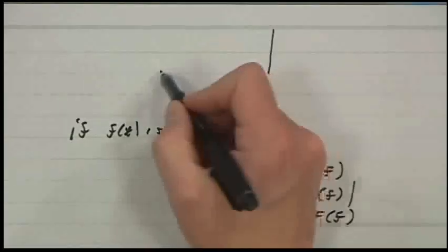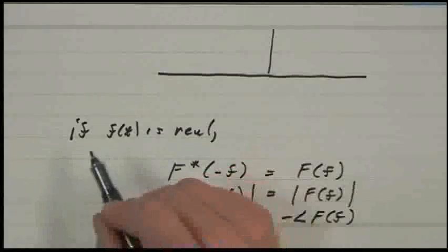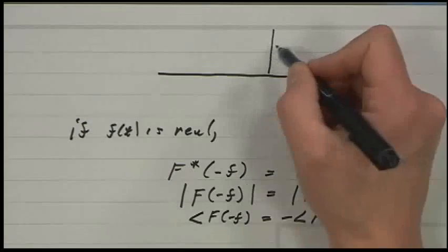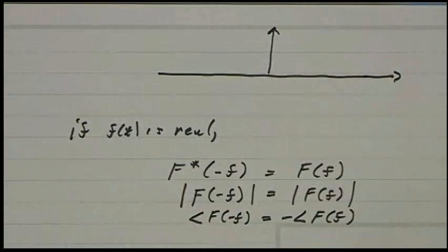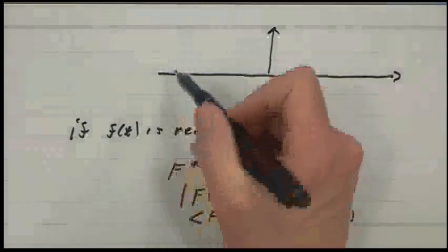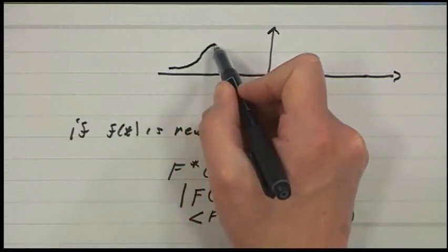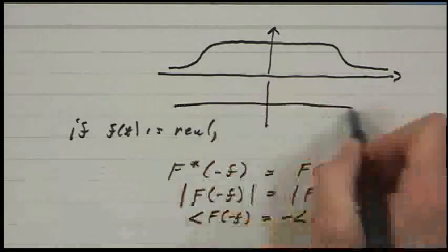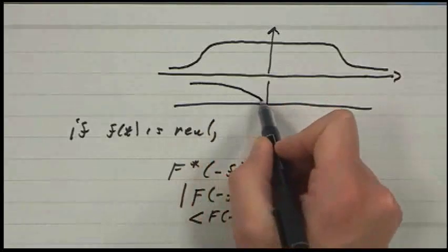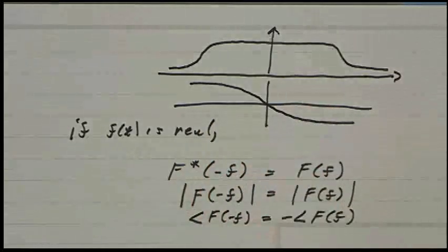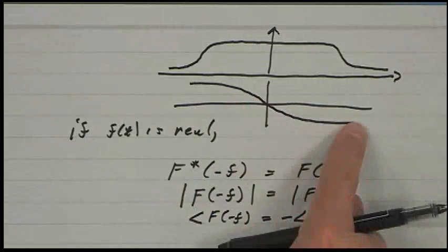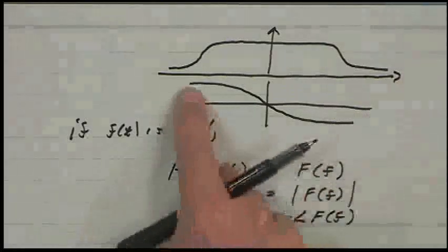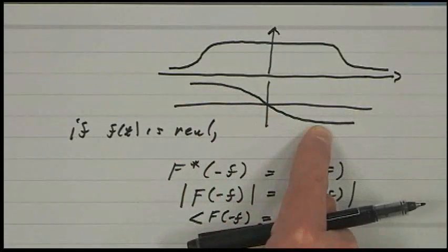again, it's going to be clear that I'm an electrical engineer, because electrical engineers love to do this. What they do, you take amplifiers and you look at the frequency response, and the amplitude of the frequency response does something like this, say. And if you look at the phase, it does something like this. So it's got to be conjugate symmetric, the phase, and the amplitude has to be symmetric. And notice that the derivative of the phase is always negative.